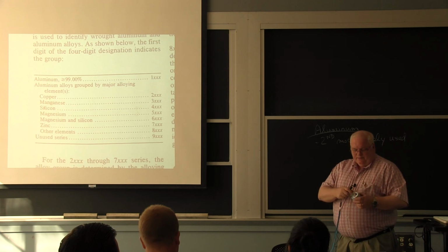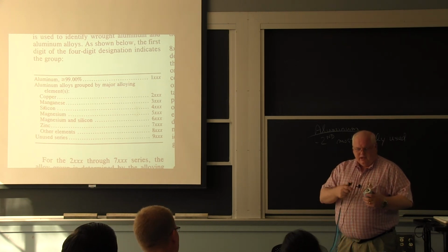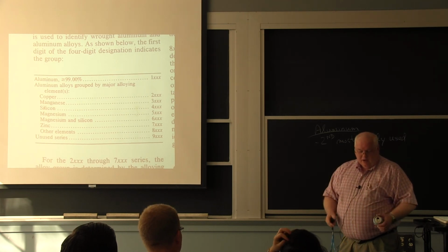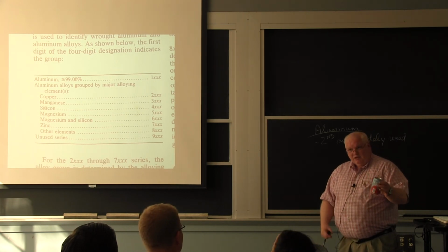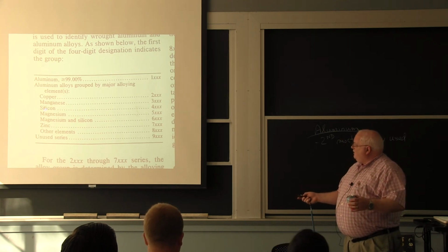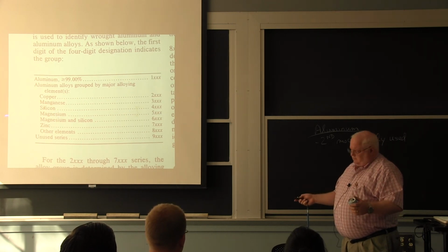The top, I think, is a 5000 series alloy because they have to stamp it. It has to have a certain strength. And the pull tab is a third alloy. And recycling these gets to be a little bit of a problem because you've got aluminum manganese alloys, aluminum magnesium alloys, and then I think the other one is also 5000 series.